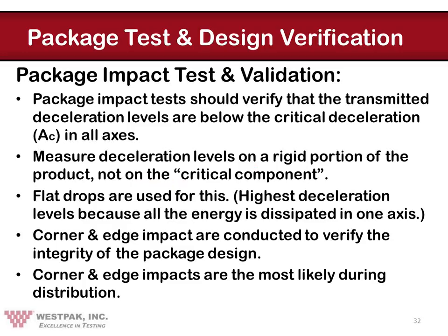Typically, flat drops are used for this because the highest deceleration level occurs when we dissipate all the energy in one axis, which is what happens with a flat impact. Corner and edge impacts are conducted to verify the integrity of the package system, and as I mentioned earlier, they're the most likely to occur in distribution anyway. So make sure you do corner and edge impacts.